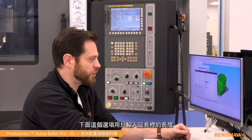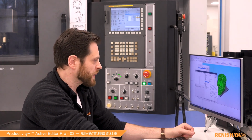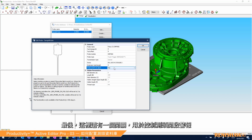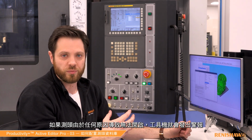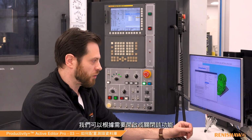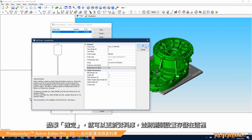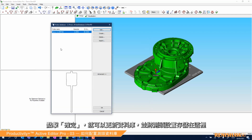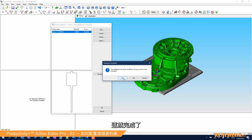Below that, there's the option to put an extension in. So if you have an extension bar to extend your stylus, you can put that in there. And then also, finally, we have a switch here, which is going to be suppressing the probe switch on alarm. So what this is, if the probe fails to switch on for any reason, then an alarm will be raised on the machine. That's just something that we can actually toggle on and off if we need to. I'm going to leave that on for now, and that's actually everything now set up for my probe. Just hit OK. That's now updated the database and stored that in there. Clicking OK on that asks if I want to save that database.